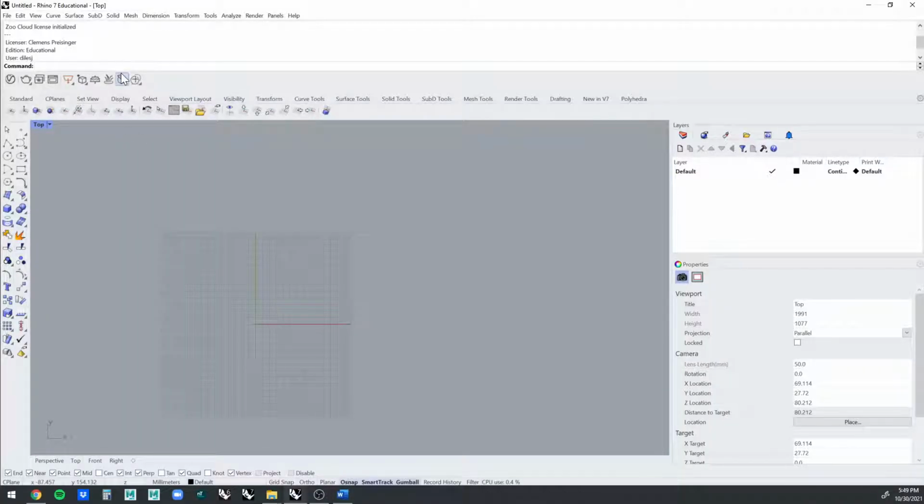All right, so let's assume now we are starting from a point where we have Karamba licensed. We've typed Karamba 3D get license. Now we are licensed. It seems that for some reason the license is very finicky when it's installed over a license server. So it's important that you always open a blank document first and then start working, and then pull in a document that you are interested in working with. Now that I have the license started, I am going to go ahead and open Grasshopper.